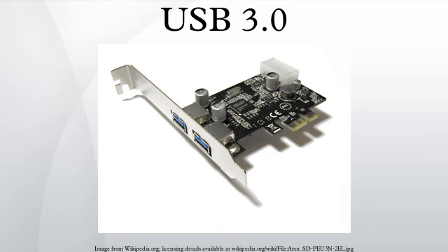USB 3.0 also introduced a new micro B cable plug, which consists of a standard USB 1.x/2.0 micro B cable plug, with an additional 5-pin plug stacked on the side of it. That way, the USB 3.0 micro AB host connector preserved its backwards compatibility with the USB 1.x/2.0 micro B cable plugs. Though, it is not possible to plug a USB 3.0 micro B plug into a USB 2.0 micro B receptacle, due to a physically larger connector.